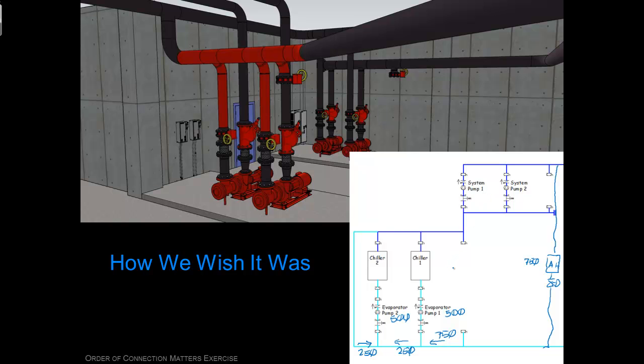And so for a while I was having these really odd conversations with people because I'd be saying primary meaning this and they were thinking I meant that, and nobody's getting anybody. So I have started saying distribution pump and evaporator pump just so everybody's clear. And I know a couple other people have had that experience too, so it does vary where you are, and so you have to make sure everybody's on the same page when you say primary versus secondary pump. But that's why they call this system a primary secondary system. You've got the primary loop, depending on your definition, the secondary loop, and then the variable flow part is what's going on out there in that loop serving the loads.